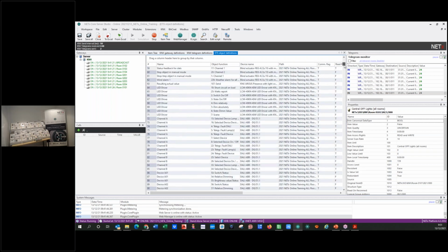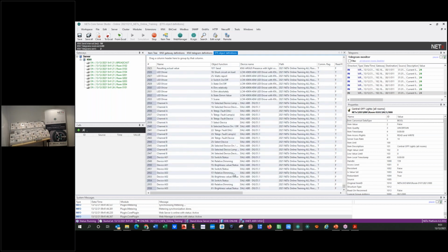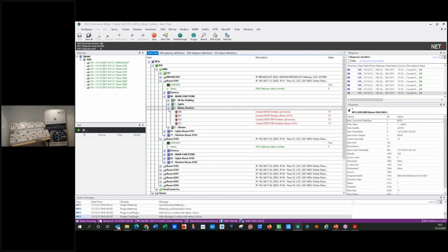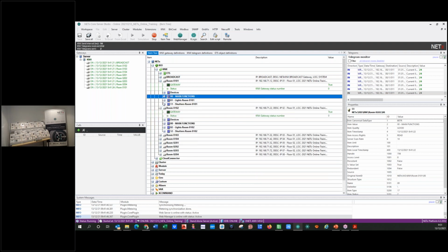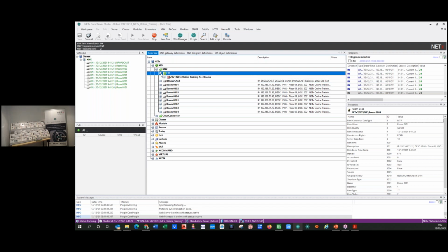So you can see here that we have thousands, almost 3,000 of objects. And what this means is a different thing than the group addresses. The group addresses is very easy to understand. I have my move, stop, whatever group addresses with 3 levels in this case, and this is easy to understand. And it is distinguished by IP gateway, in this case by the name of the IP gateway. So they have different branches, but the objects are in a different way.